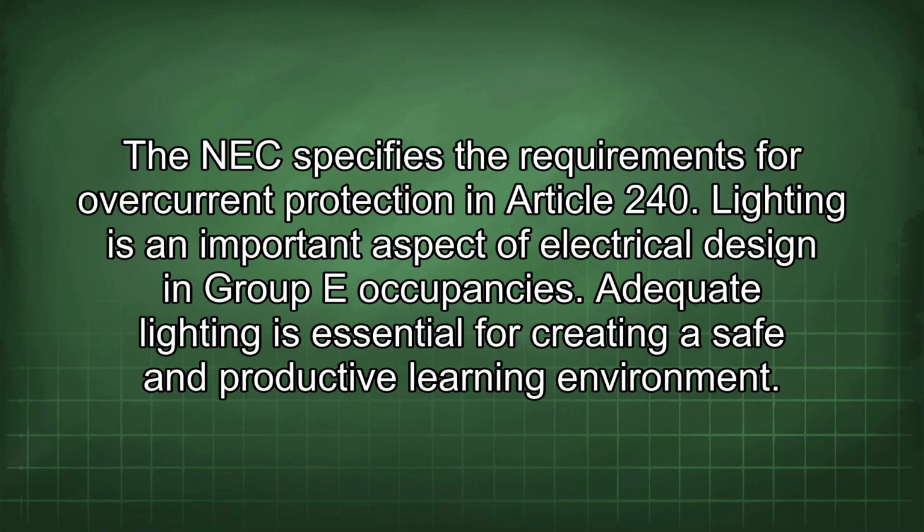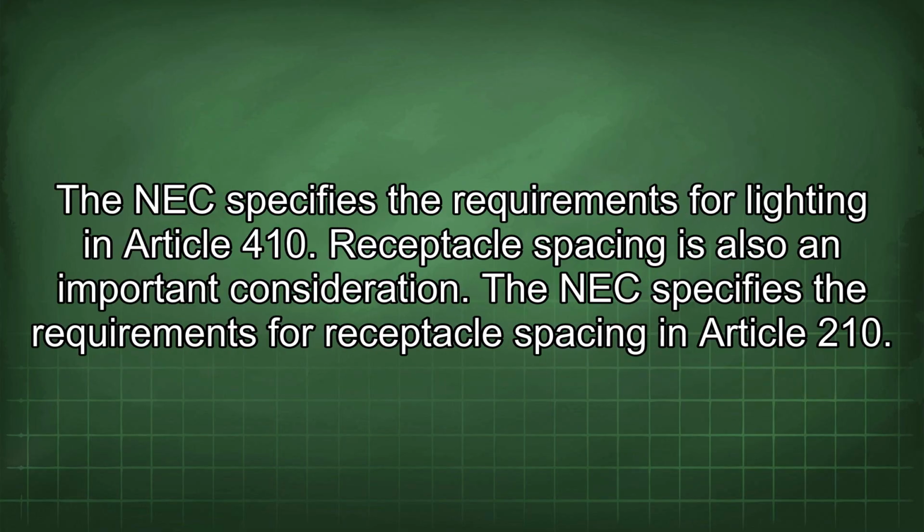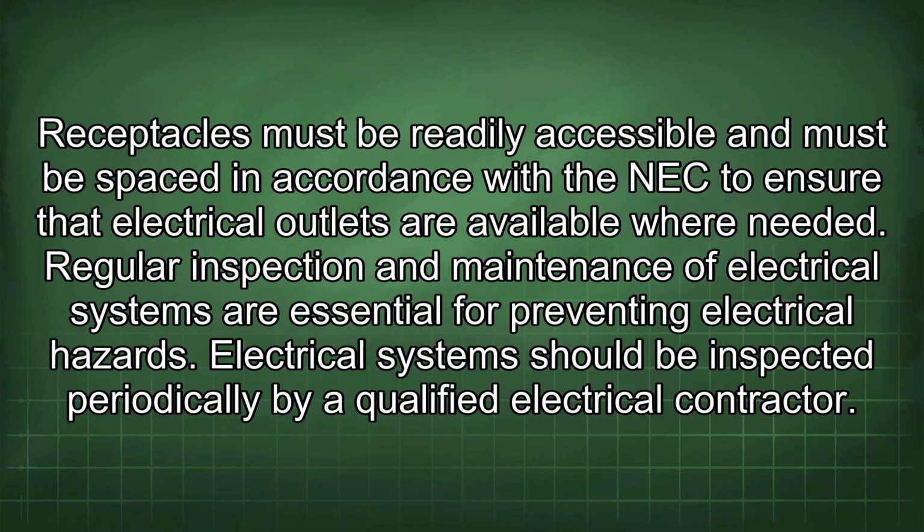Lighting is an important aspect of electrical design in Group E occupancies. Adequate lighting is essential for creating a safe and productive learning environment. The NEC specifies the requirements for lighting in Article 410. Receptacle spacing is also an important consideration. The NEC specifies the requirements for receptacle spacing in Article 210. Receptacles must be readily accessible and must be spaced in accordance with the NEC to ensure that electrical outlets are available where needed.